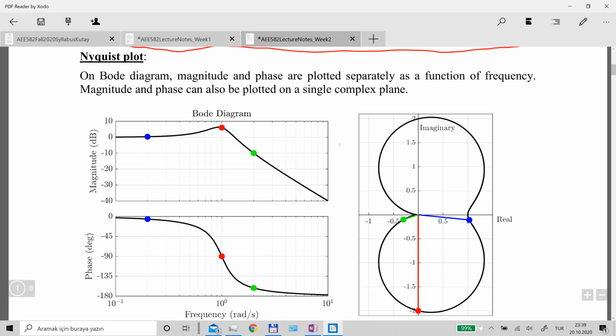So when you repeat this exercise at several frequencies, you observe a different magnitude and phase variation. And when you plot them as a function of frequencies on two separate charts, you obtain what is known as a Bode diagram. Okay, so in a Bode diagram, you give an oscillatory input. Let's say this is your frequency. You calculate or measure the change in magnitude and phase, and you plot them here, and you repeat this for a number of frequencies, and this is how you obtain this chart.